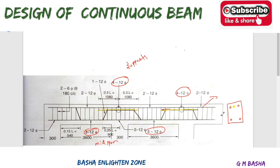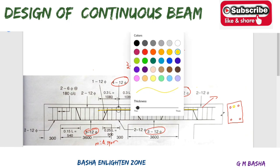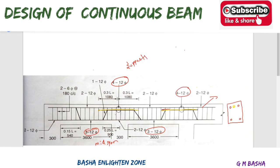If you observe, there will be 2 bars on the bottom side also, and this full bar will be cranked. I will show it with a different color. See here, it comes like this, and again it comes like this. They take one full bar and crank it like this. If you see, the bar will be cranked like this here. It covers both top and bottom. From the side view, it will appear here and here. The bar covers the rear supports like this. So minimum 3 bars will be required on the top and bottom side.